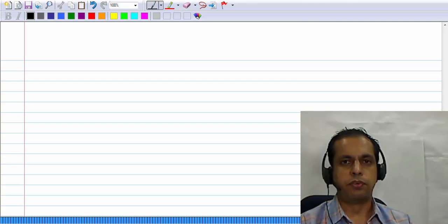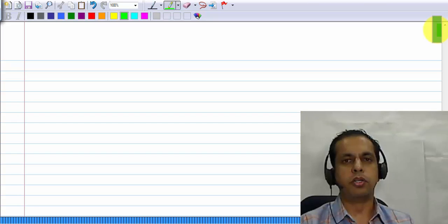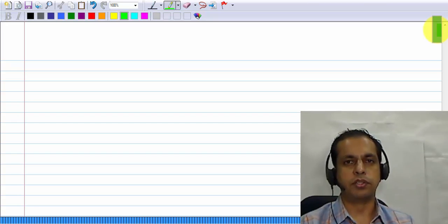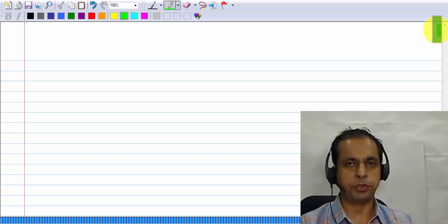We have discussed four varieties of biasing a transistor at a given current I0, and central to all these circuits is negative feedback. So far our discussion has focused on the sense of negative feedback. When you use these things in an amplifier, you also want the transistor to be in saturation region. So you have to get the sense of feedback correct, as well as the bias voltages and so on correct, so that the transistor remains in saturation. Now we will discuss a few of these issues.